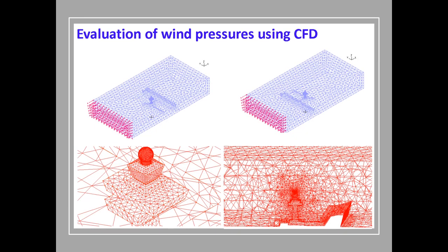The control tower and its adjacent structures were included in the computational fluid dynamics finite element wind analysis study. The wind computational flow domain employed was 2,000 feet long, 1,000 feet wide, and 358.6 feet high. Design wind velocity of 150 miles per hour was used at the radome base.